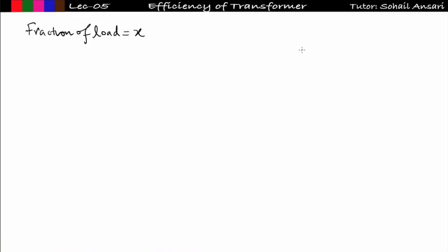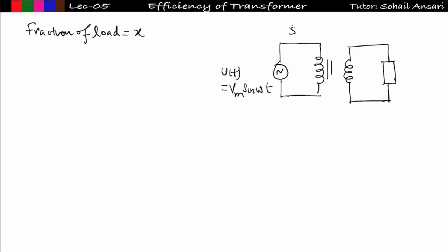Let us try to analyze this fraction of load practically. Suppose we have one transformer, and I am considering this as an ideal transformer. Now this transformer has a rating of 10 kVA. This is the rating of the transformer, and let us say this is a step up transformer, with number of turns 100 is to 200, and I am considering this ideal transformer. Got it? Now I am connecting a load. This load has a 1 kVA rating at 0.8 power factor. This load is consuming 800 watt of active power.